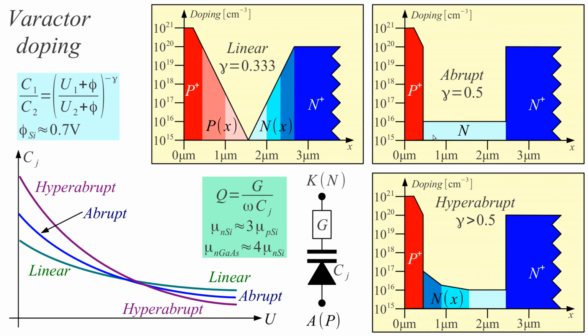So with the depletion region extending into the N-doped region, we get a better Q than with the P region. So we usually design the diode in such a way that we have no depletion in the P region. Depletion there is damaging. It is destroying the performance of our diode. But we will grow our depletion region into the N, so we dope less N to have the same charge at a much larger distance.